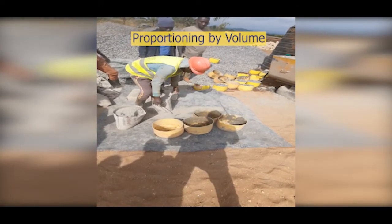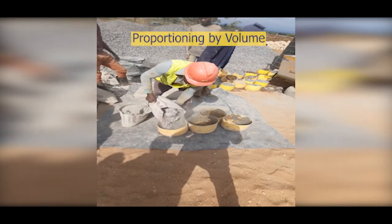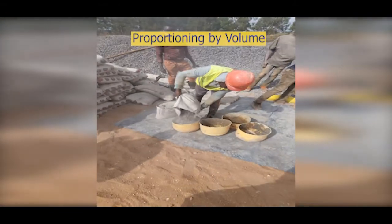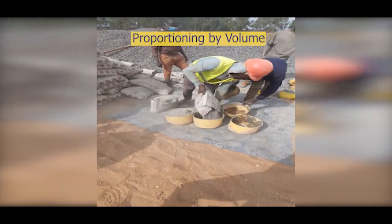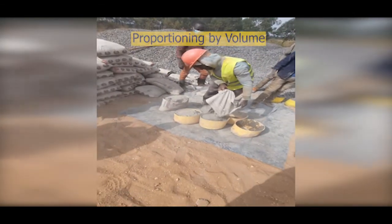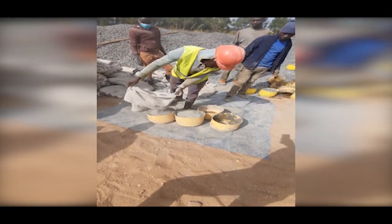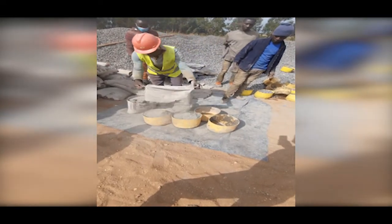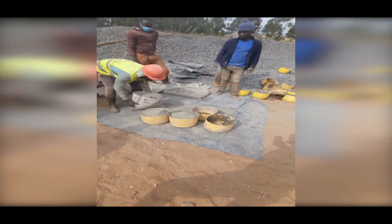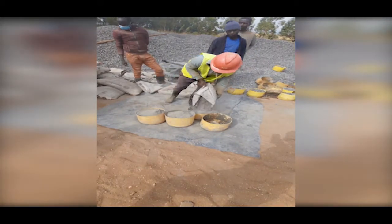That means where it's going to be used, what sort of loading and stresses are going to be expected at that point, and that sort of thing. So typically there are some standard mix designs for concrete, ranging all the way from a target strength of 10 all the way to 25 Newton per millimeter squared. So anything above 25, usually a mix design is done.